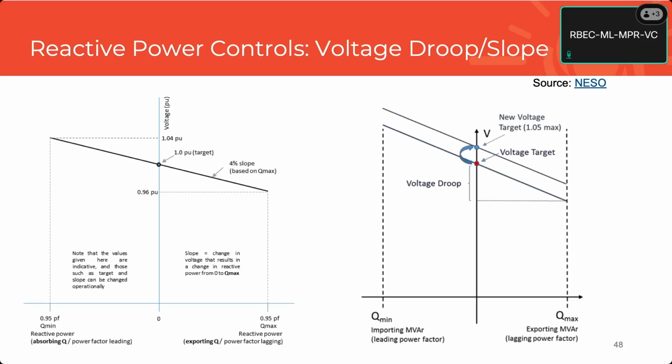And this is a steady state controller. Yeah, it gets a lot more complex when the voltage set point continues to move every time you change reactive input. I think you mentioned it briefly, but deadbands can also help with the hunting, right? If you have a little bit of deadband, which is simply an acceptable amount of error. It literally helps you place where the controller stops listening. It's a dead section in your controller. And that also helps the hunting.